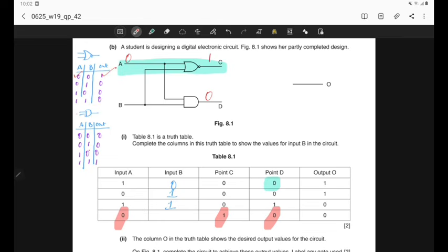There is only one option, the first row in the truth table, where we can see when 0 at A and B only we will get 1 as the output of a NOR gate. That means here the value must be 1. So we can complete the table that input at B also must be 1.